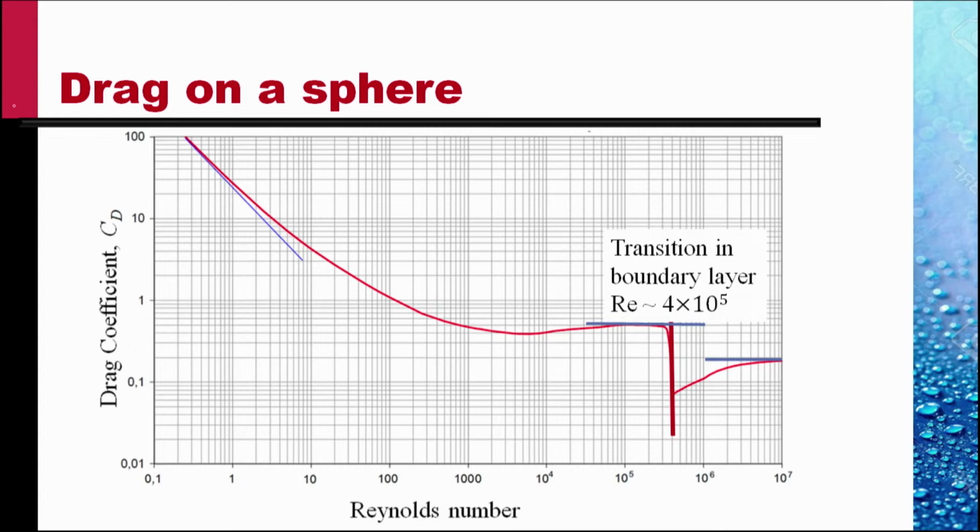There's a little more pressure recovery, and so the pressure drag reduces. Though, of course, as was mentioned in the last lecture, the shear drag or the skin friction drag has increased slightly. But the skin friction drag does not dominate. What dominates is the pressure drag, and so a reduction in pressure drag leads to reduction in the drag coefficient.